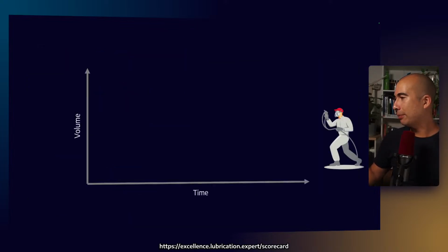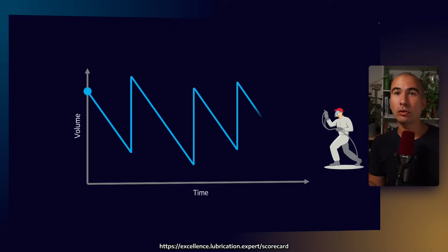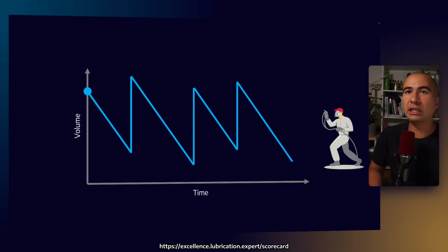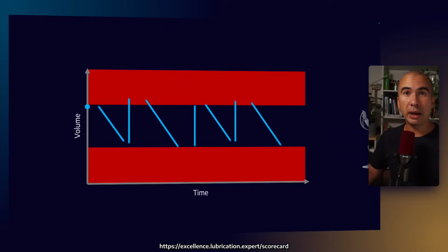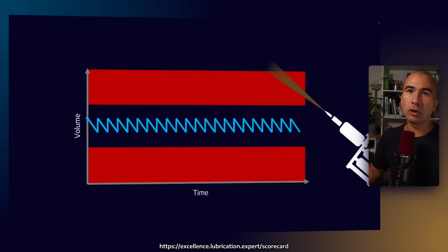Okay. All right. Now, lubricant application, as we're starting to get into the home stretch here. When we apply lubricants manually, let's say, for example, we are re-greasing a bearing, we are returning to the asset once every now and then. The problem is that sometimes we can overshoot or undershoot the ideal amount of lubricant. So we have automation methods which enable us to lubricate on a more frequent basis, but with less volume, which can enable us to kind of thread the needle.